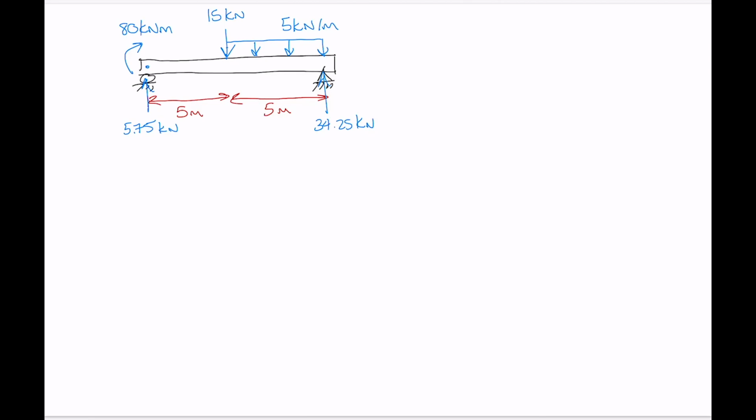Okay, so when we draw shear and moment diagrams, we always do a sort of a 3-tier stack. So it's always free body diagram at the top, shear diagram directly below that, and moment diagram directly below the shear diagram. And as we learn how to draw these, you'll get to see why we set them up that way. So I'm going to set the axes up for my shear diagram here. Here we go.